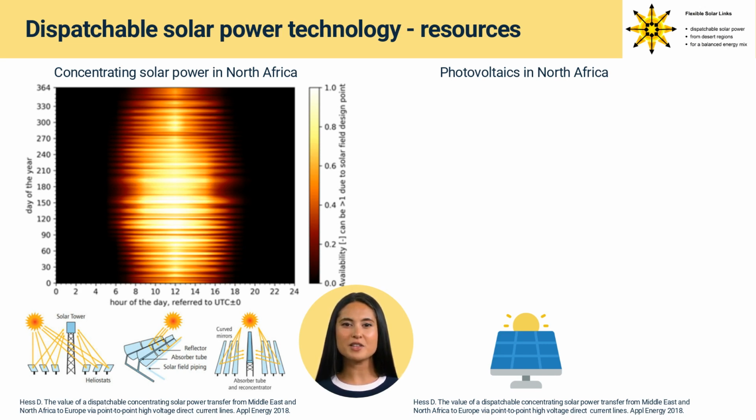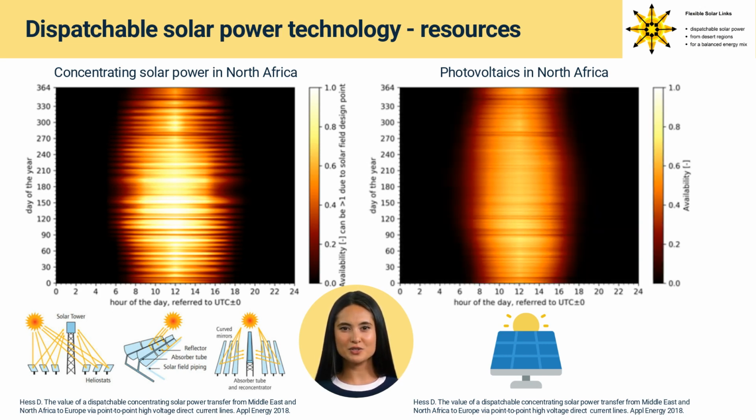However, this high availability is not perfectly continuous and rather scattered. This is the case due to clouding and absence of direct normal irradiation. The yield of the photovoltaic module has also a high availability during noon and a smoother trend due to almost constant available global horizontal irradiation. However, the intensity of the availability is not that high compared to the concentrating solar power collector, resulting in a lower efficiency factor of the photovoltaic module.